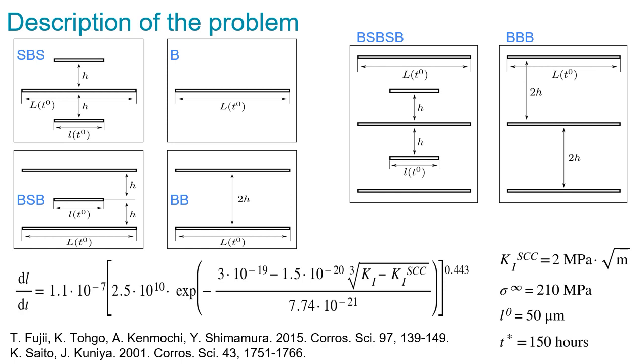Shielding effect was studied by many authors for cracks of equal size and for two cracks of different sizes. We are focusing on studying the shielding effect caused by interaction of larger numbers of parallel cracks of unequal length with various relative distances between them and their centers located on the same vertical line. And we wanted to check whether the circular relaxation zone around the pre-existing crack may suppress the growth of other cracks inside it in any stack configuration.